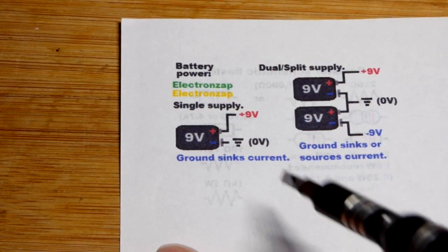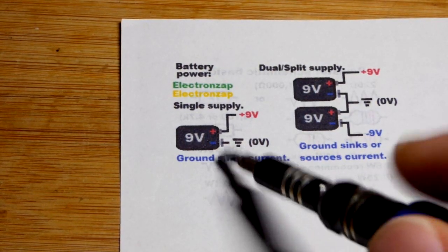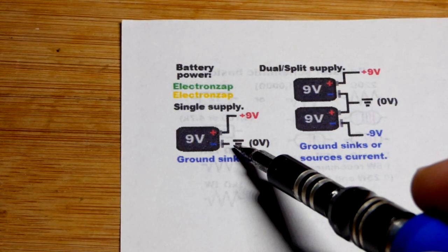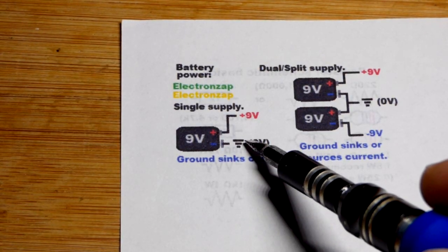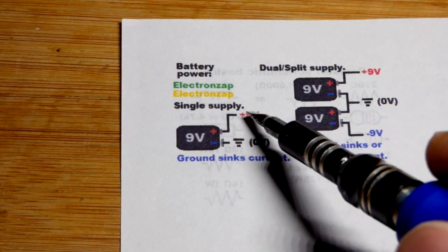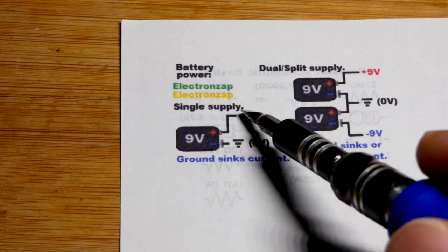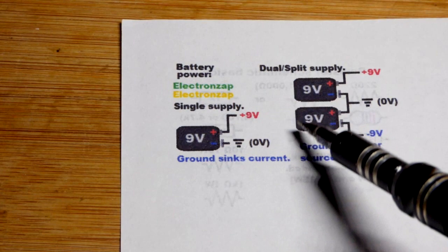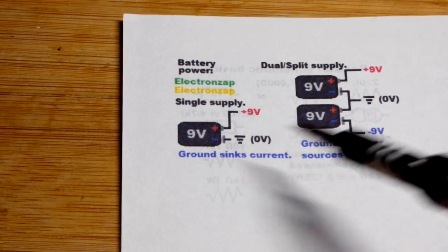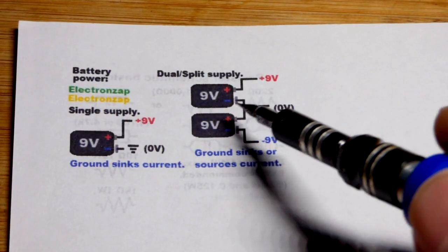So now in basic electronics, usually you're using a single supply. Let's say you got a 9-volt battery, the negative side is ground, then you got a positive voltage in relationship to that. That's the battery voltage, 9 volts right there. And you design your circuit to kind of be within that voltage range right there.